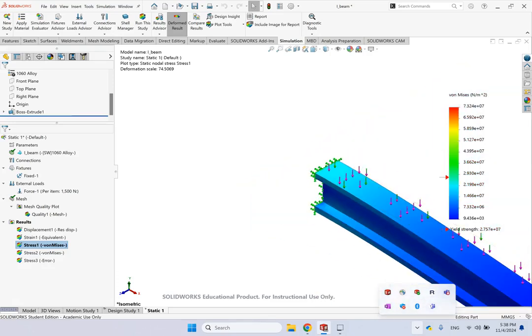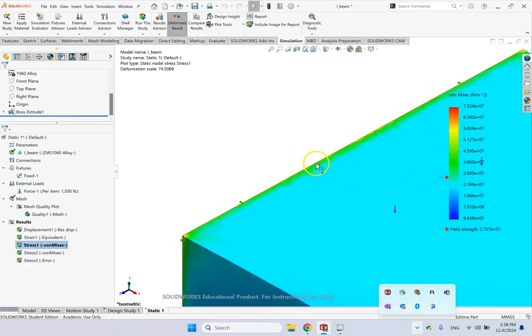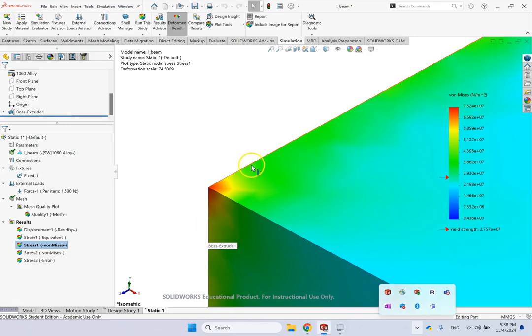So remember, this is a simple 1D problem, and you expect the moment to linearly increase and get to the maximum at this very edge. So at this edge, you should have maximum stress, which you see right now you do. And then nothing in this Z direction is different. So when you move here in the Z direction and you go from these green values all of a sudden to a red hot spot, that is an indication of a numerical problem.